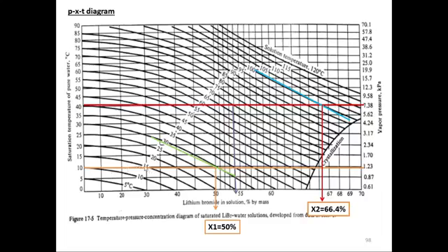So the brown line and the red line, the corresponding vapor pressures of water are 1.23 and 7.38. So these are the pressures in the absorber and in the generator. The solution temperature in the generator is 100 degrees centigrade.